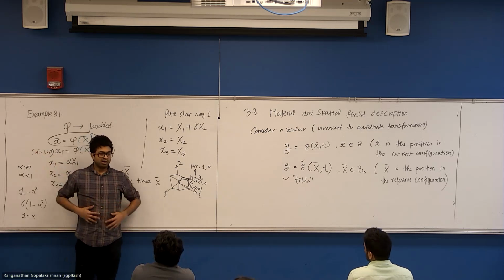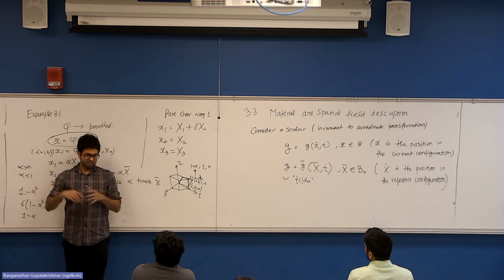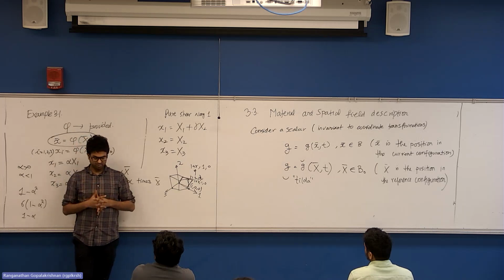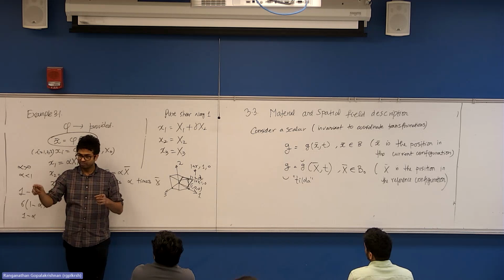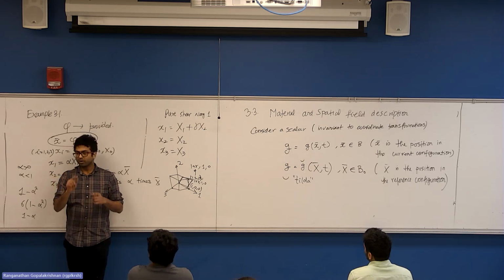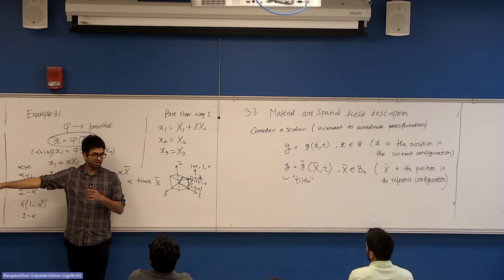Okay. So I'll try to give some examples from different measurement sciences. If you are familiar with fluid mechanics, suppose you take a velocity probe like a hot wire anemometer, you stick it in a certain volume, certain point in your flow. And the hot wire anemometer basically produces a voltage which is proportional to the fluid velocity at that point. And you read out the velocity as a function of time.